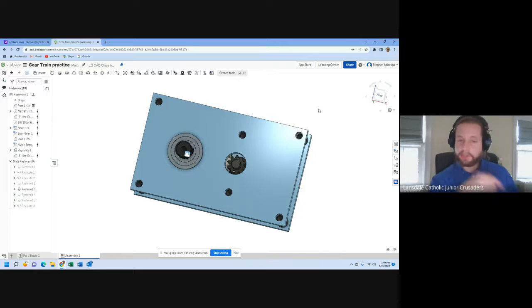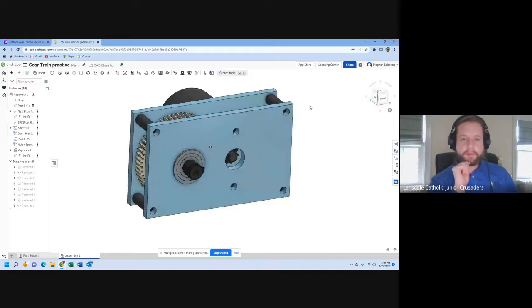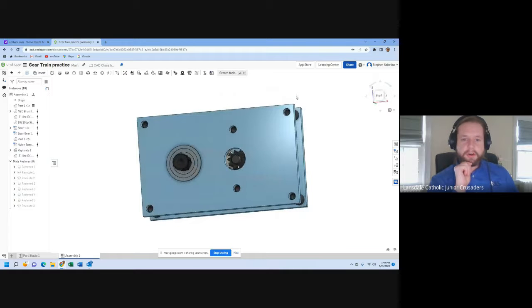And if you click the J button, it does the same thing with mates. Okay? Okay. So now what I want you to do is, you should have a Revolute mate for your pinion gear. So right click on your gear and hit show mates.